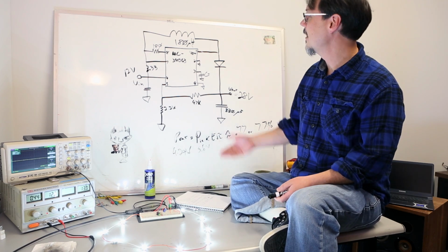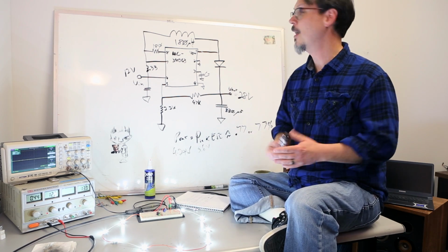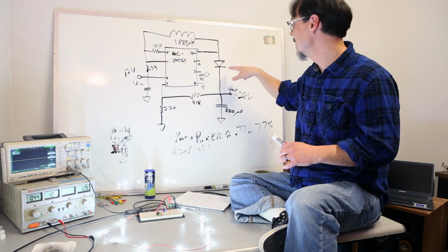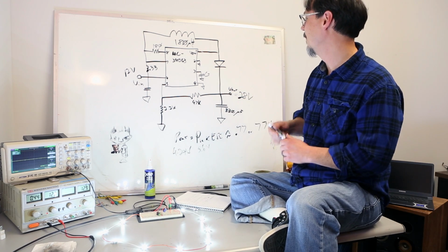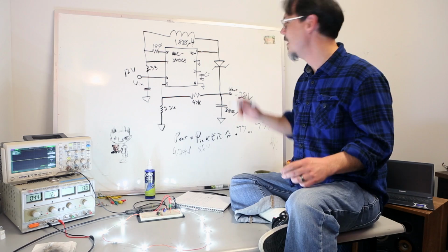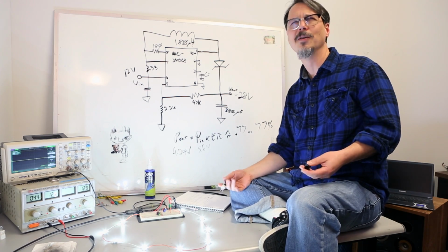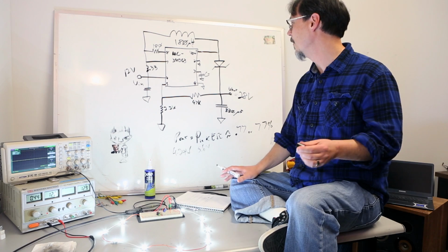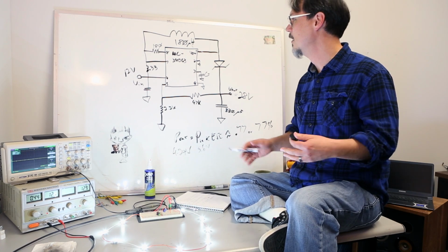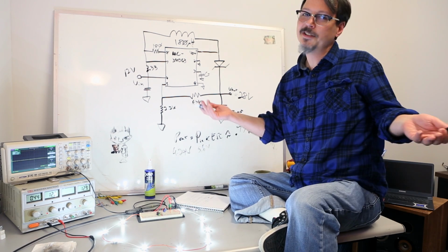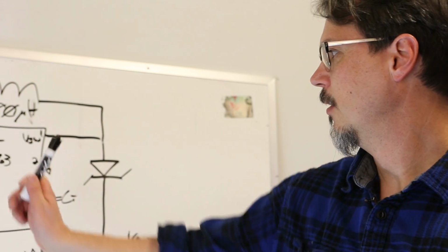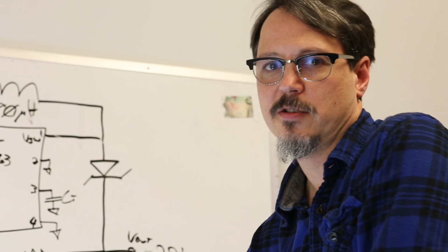Other reasons, like I say, my component values are not optimized. I'm running a different inductor. My diode is not their Schottky, right? They want a Schottky in this place. I've got like a 1N4000 something series, so it's a rectifier diode, not a Schottky diode. Totally not optimized for this. So I'm running less than 87%. Not a huge surprise. That is boost regulators, quick and dirty.